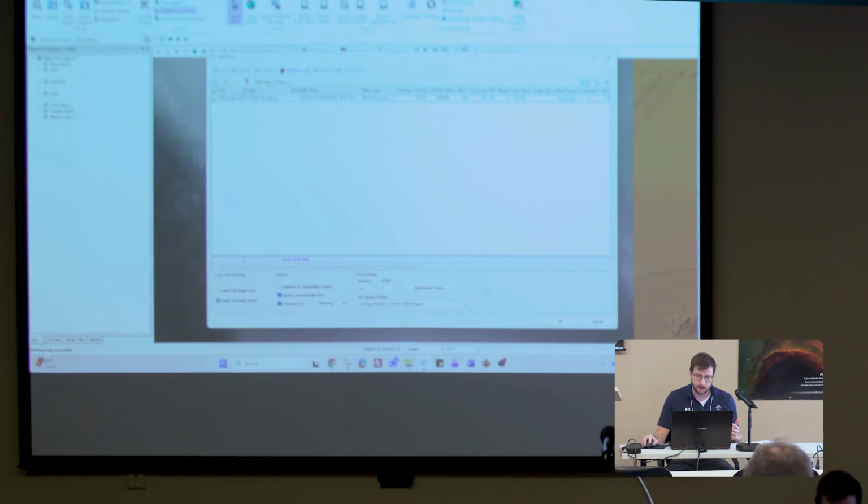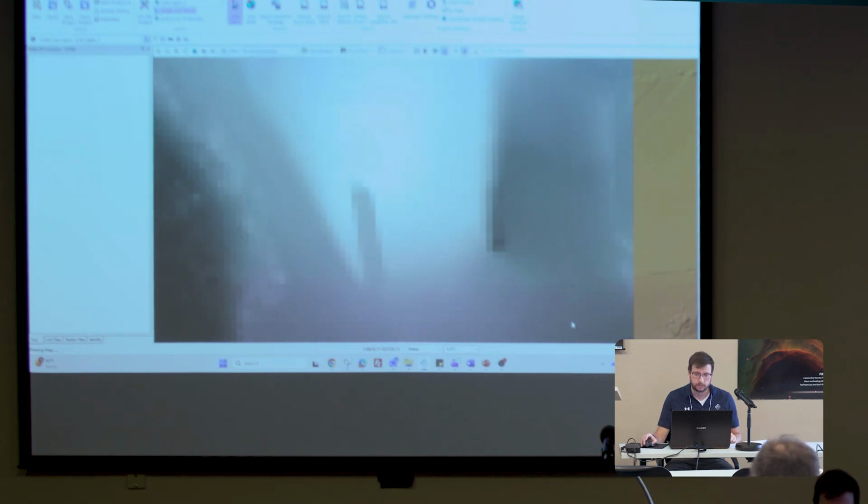One of the things that I like to do, usually we're making this based on ground only, so destination class, it's going to put all the points we're creating in a single class. So if you don't choose a class, it's just going to put it in class 0, created never classified. I'm going to select ground because I know that that's where the data originated from, and click OK.